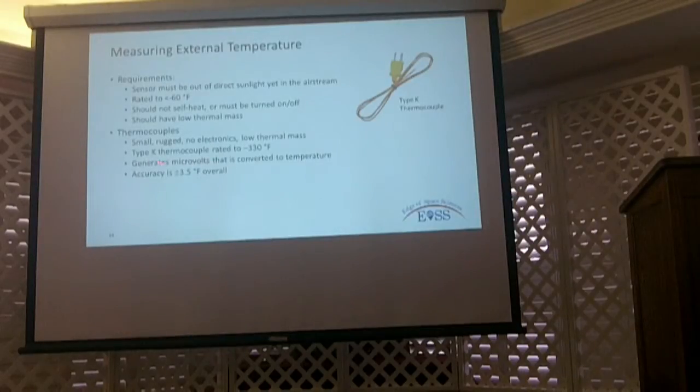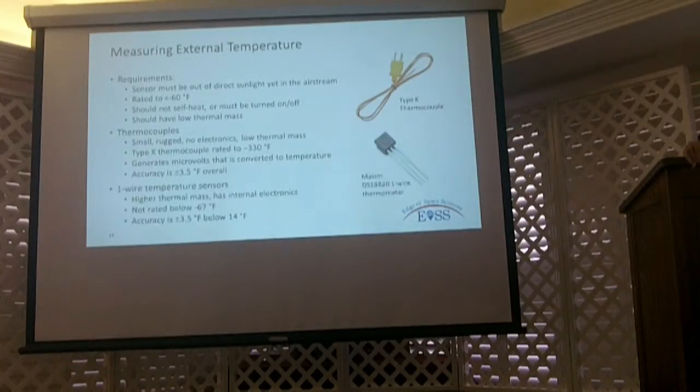They generate microvolts, and that is converted to temperature. And the nice thing is there's a chip that does that. You don't have to try to read microvolts. The other way to do it is with these one-wire temperature sensors. I know a lot of people have used these, and they're the Maxim DS18B20s, and so on.